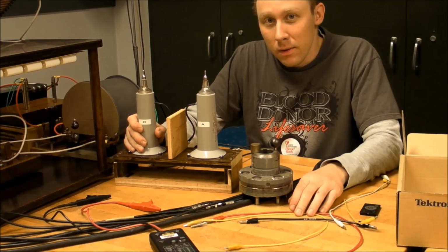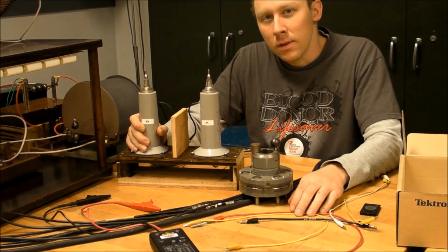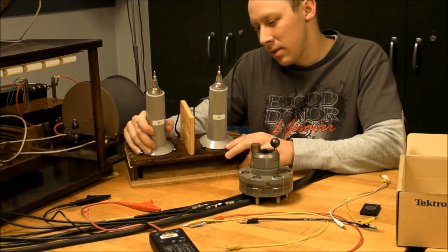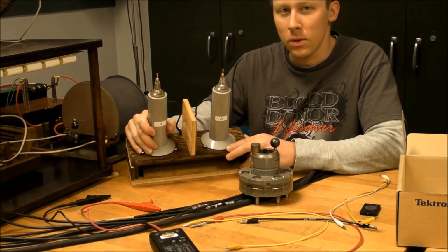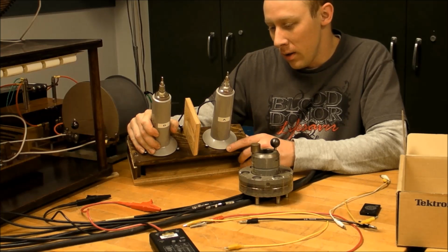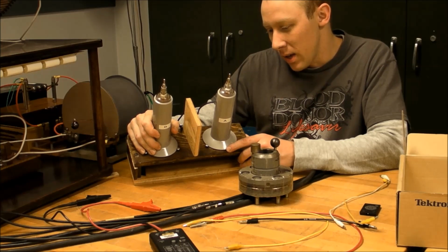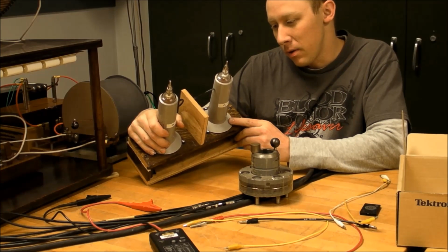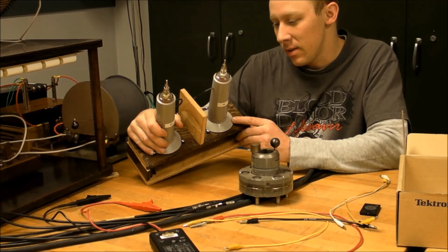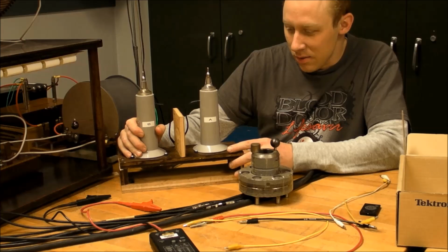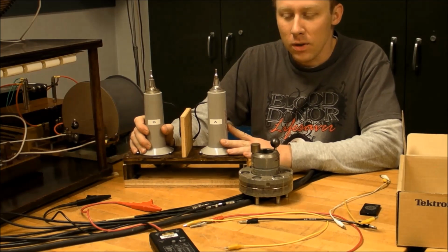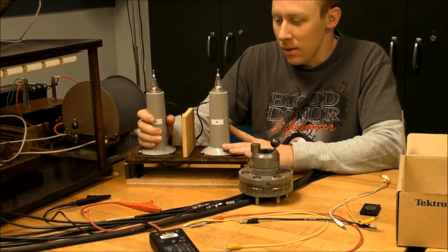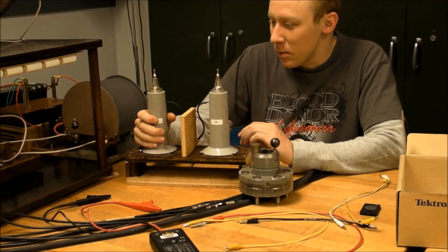Well, there you go. We got a lot of data today, but unfortunately most of it is going to have to go in the trash because of these things right here. These are Tektronix P6015 1000 times high voltage probes. Let's see, 20 kV maximum DC continuous, and they say above 100 kilohertz see derating curves. So that essentially means that this has a 100 kilohertz bandwidth, and since I'm operating at 100 kilohertz with my Tesla coil, these are unfortunately not going to work.